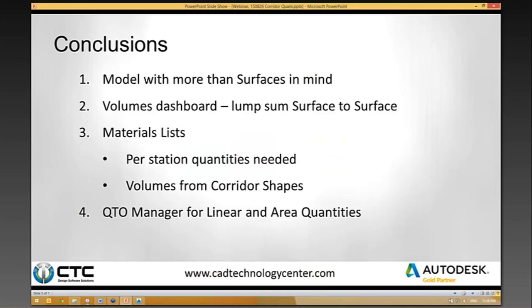So that's mostly what I wanted to show you guys today. Just a few conclusions to draw from this. I imagine people are all different levels watching this, but the big part of this is you have to model a corridor with more than your surfaces in mind. You have to be modeling what's out there. So one of the questions was, well, what if I want to do asphalt and concrete? You have to differentiate that in your corridor. That's done through coding, okay? You have to model what's out there.